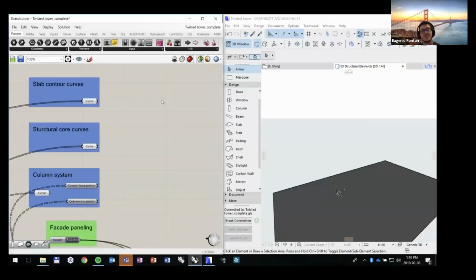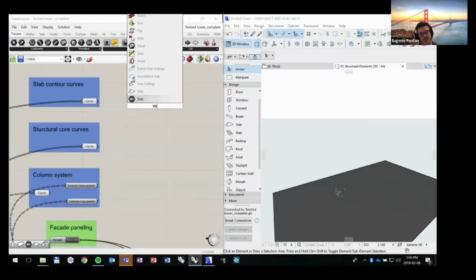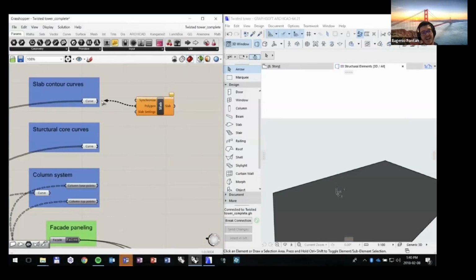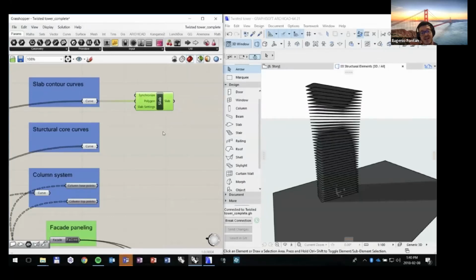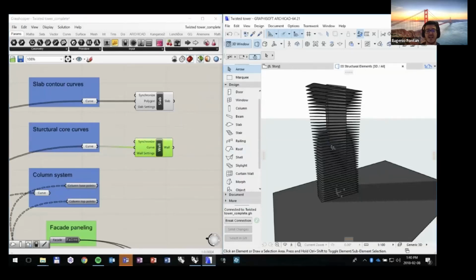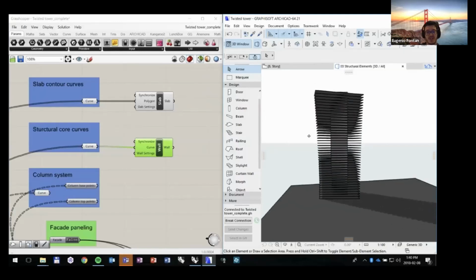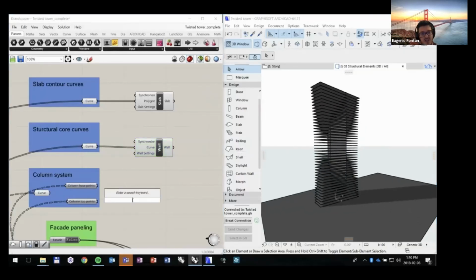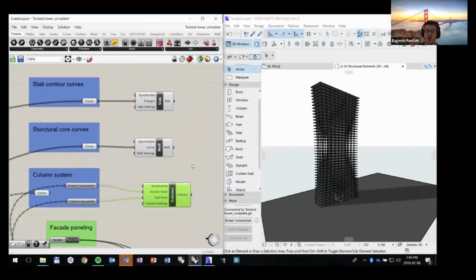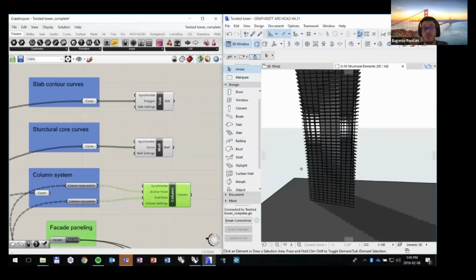But when we go into Archicad, and now we have Grasshopper on the left side and Archicad on the right side, Archicad gets all these contours, all these curves, and converts them into real BIM elements. In this case, slabs, elements that have information, geometry, quantities; we can extract dimensions, parameters, and documentation. So Archicad completes this stage in which we can create a fluent workflow, in which our design basically becomes the virtual project. And then from there, we can keep making modifications, and the model in Archicad, the project, will be updated.